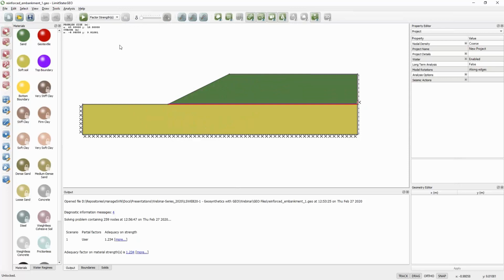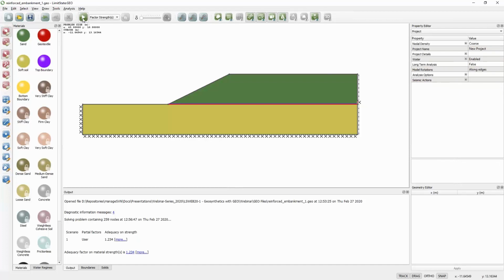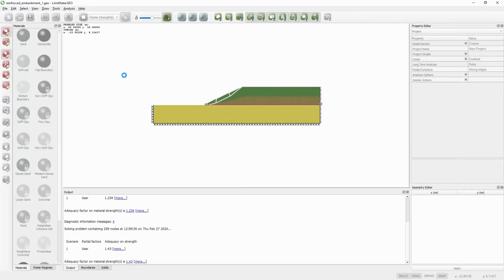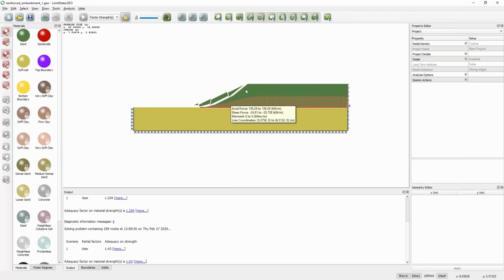So, for example, if I make my geotextile very strong, so I'm going to just up this from 25 to 250 kilonewtons per meter, then the software will determine that actually before we get that large combined failure mode, because of the reinforcement that's much stronger, we're going to get to a slope failure on the embankment first before failure would occur in the combined embankment soft soil body.